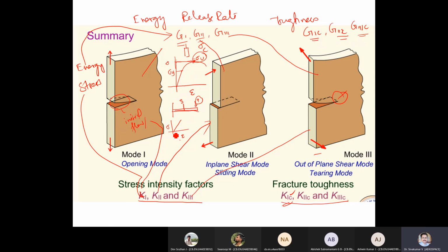So what is this stress? When the body is subjected to forces, it creates an instantaneous stress at a particular point in time, at a particular location. So when will failure come? This instantaneous stress will be less than sigma u, isn't it? So what is sigma u? It is an experimentally tested material characteristic. Sigma is the on-field value.